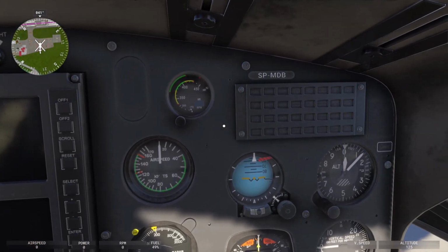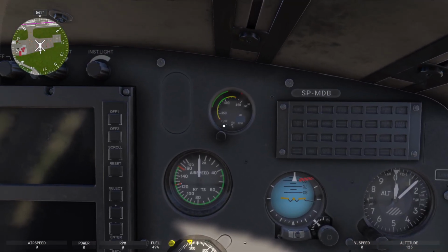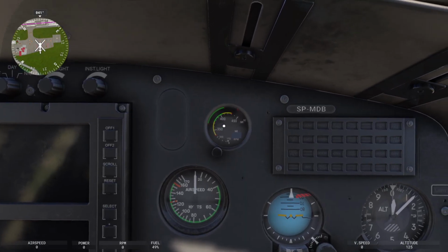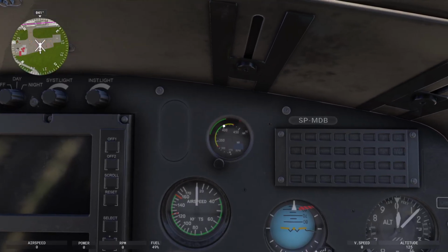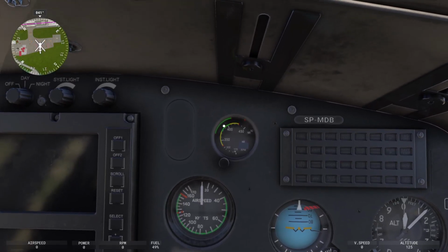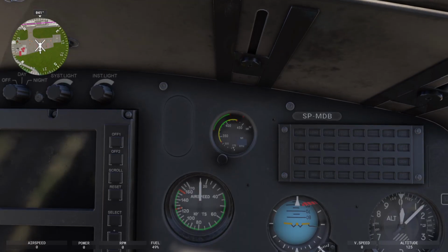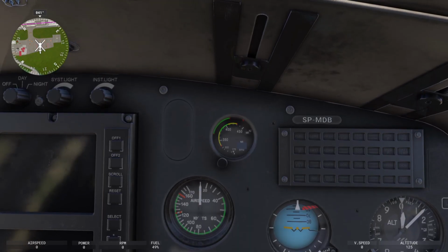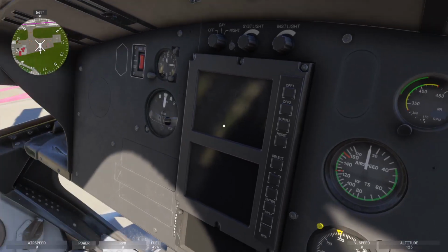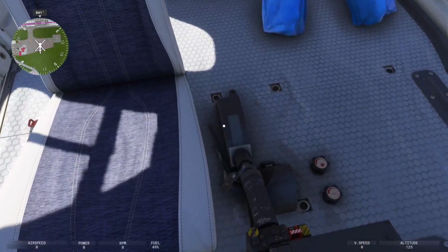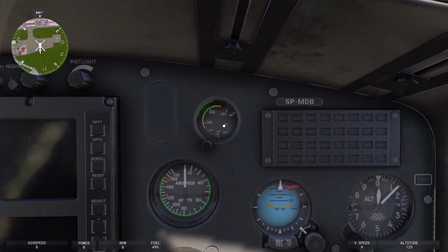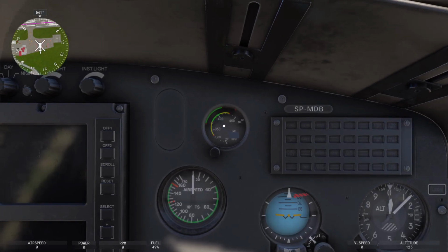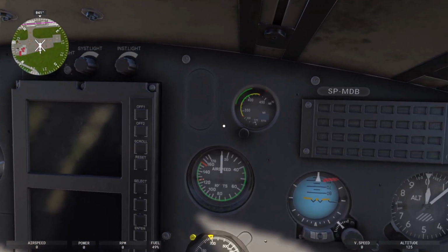Here you have NR. Okay, N is a figure of how fast something's going. Okay, so it's speed. The R is rotor. Okay, so this is our rotor speed. Most conventional gauges now have the amber, yellow, and green zones. Obviously, what we aim to do is keep that NR in the green. It does that efficiently by using a FADEC system. This aircraft will have one. It's basically a computer that manages throttle. Okay, it manages fuel and all the elements required for keeping the rotors turning at 100% RPM.